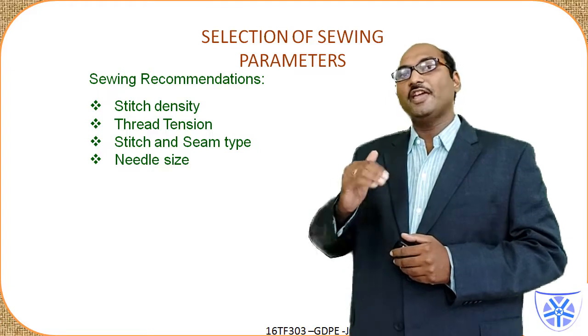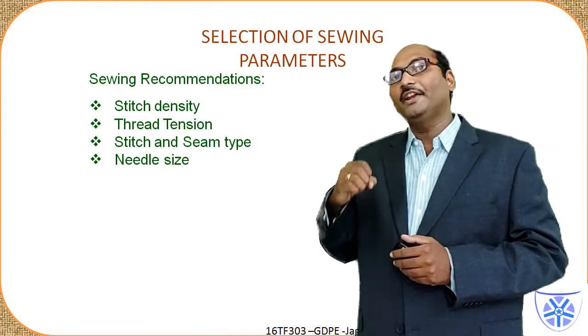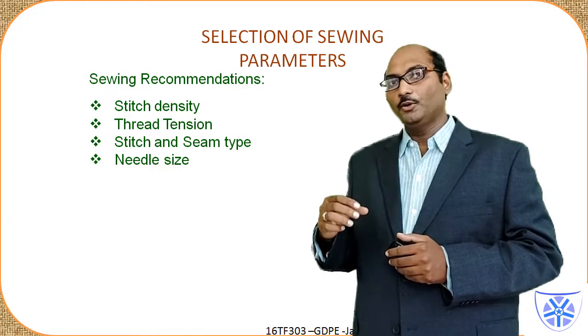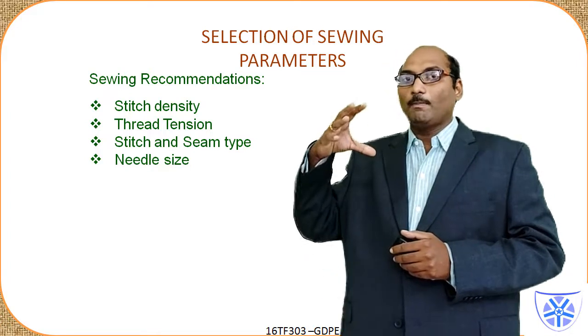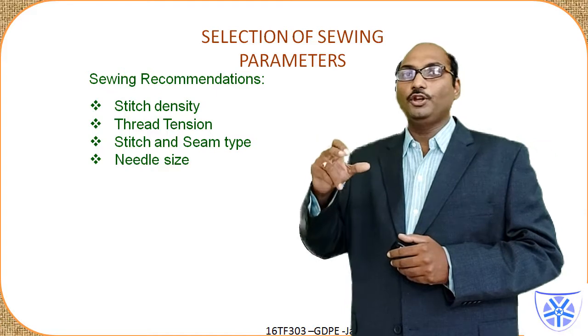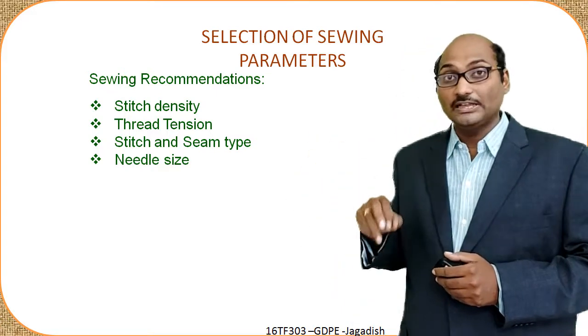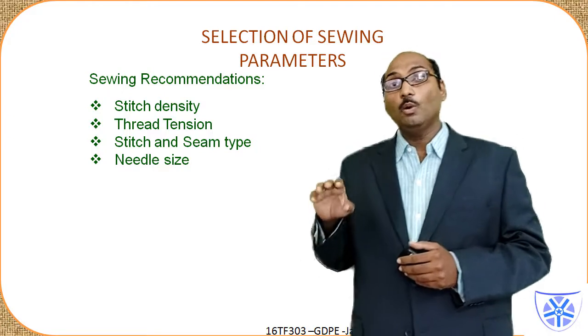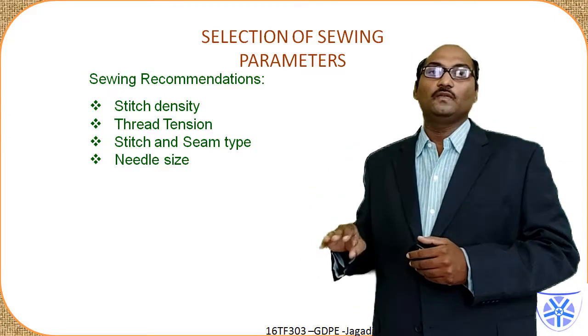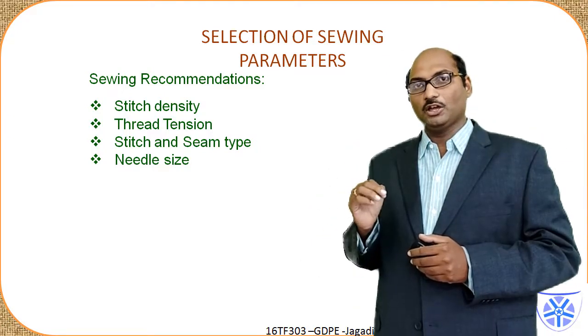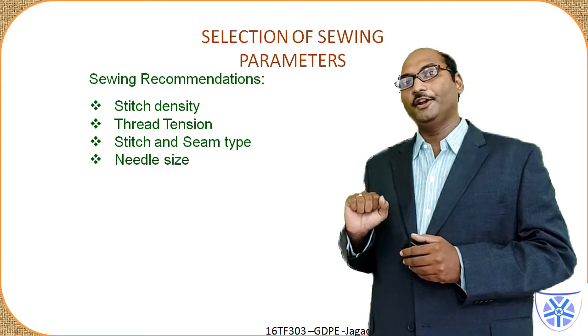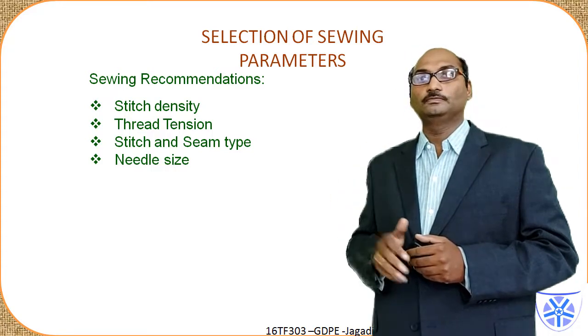Again, during the dyeing process, shrinkage might happen. So, in order to avoid puckering of the seams, we need to maintain slightly less thread tension, such that it will be okay even after the dyeing. The seams are very much controllable, and they will look good.